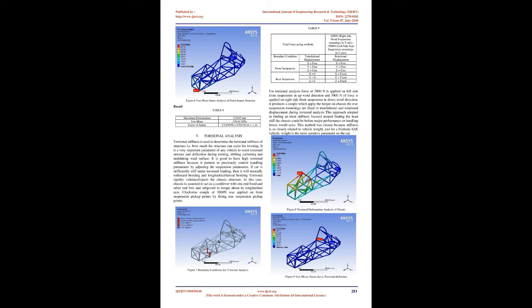The front impact analysis is done to find out the amount of bending stress as well as deformation generated in the FSAE chassis if the car hits a solid body from the front, whereas it is more likely to happen in any worst case. In order to simulate the frontal impact crash, the vehicle was assumed to impact upon a stationary object. Upon research it was found that the maximum force that a human body can withstand is 5 g.